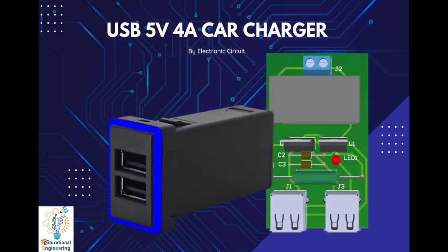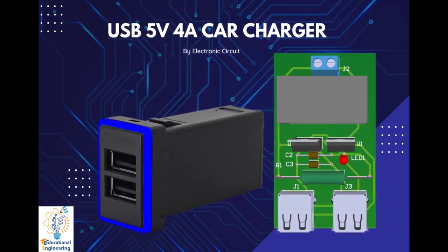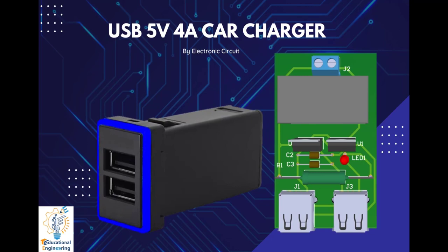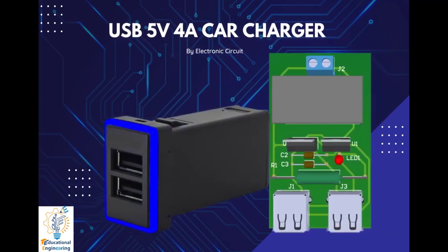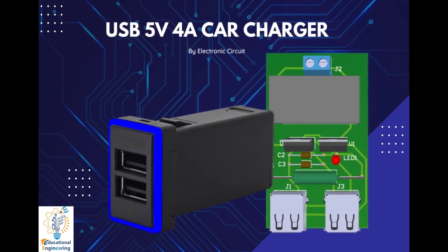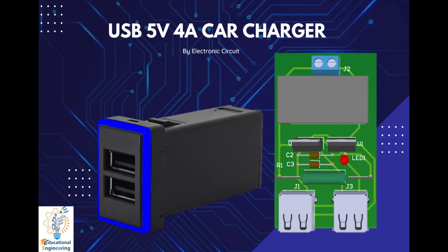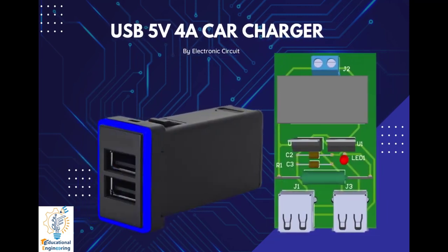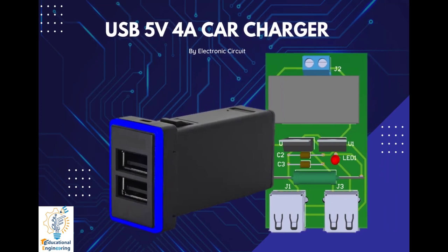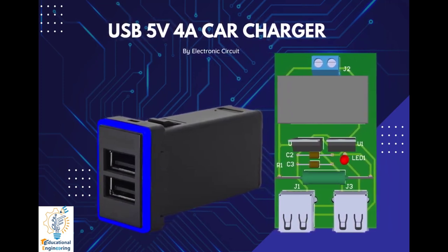This is originally made by Electronic Circuits. It is a simple PCB that charges a cell phone, tablet, or any other gadget that requires a voltage of 5V with a current of 2 amperes via USB. This is a DC converter that takes power from a cigarette lighter socket in your vehicle and converts the 12V battery voltage to a stabilized 5V voltage. So let's go to Altium Designer.